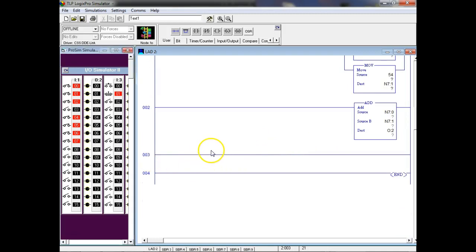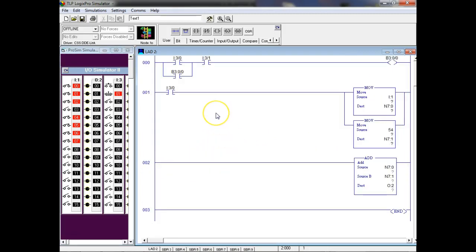I had to delete this wrong drop. So this is the way ours would work. Now, how would we disable everything? What we do is we come down here in all our rungs and put a what? And that's nice when using symbols because you don't have to remember your address. No, because it would still do the math.